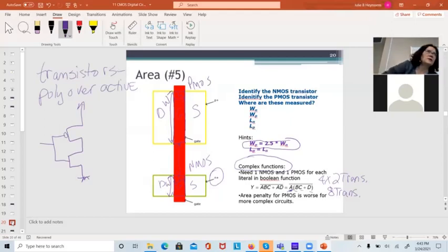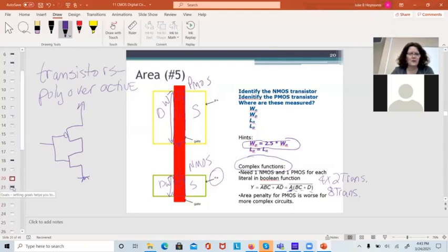And if I come up with a circuit with more than that, I know I can reduce it. And if I can simplify the Boolean expression, I might be able to do it with a fewer number of transistors. Okay. And then in 380, we learn tricks to make the 8 go down to a fewer number. In dynamic logic, you can do it with 6 transistors. And pass transistor, I'd have to draw it out, but you might be able to get by with 4.